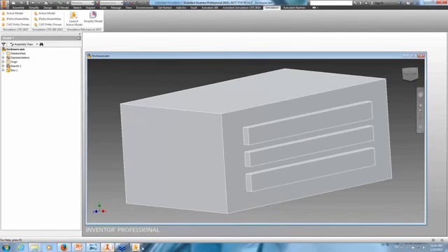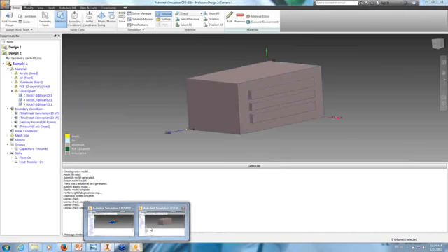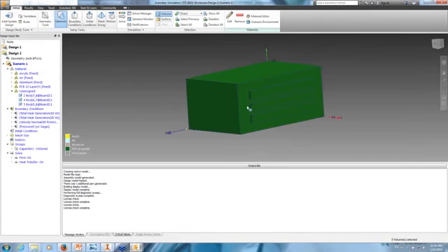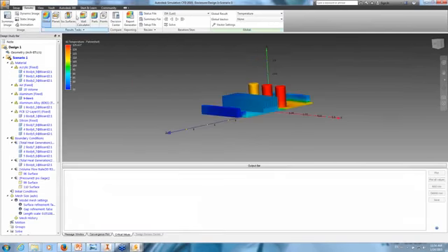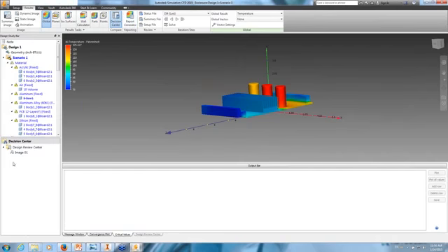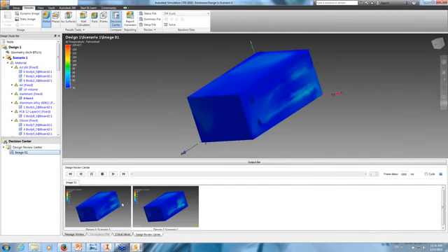And what that will do, if I go back to my CFD here, you can see that it added a 3rd outlet, and I can go back and check and make sure that all my boundary conditions are proper and rerun the analysis, and then I can use the decision center to, you know, create images and compare side to side.